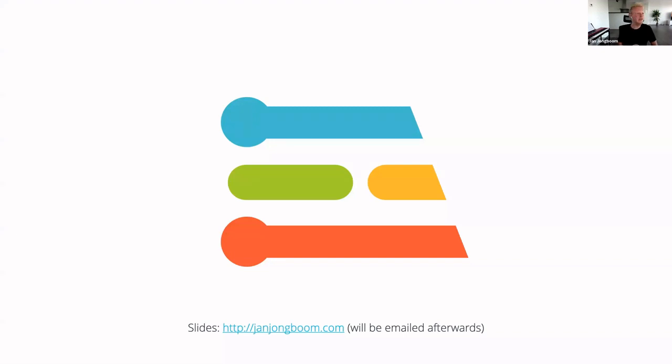What we see is Cortex M. I would recommend a Cortex M7 for doing this stuff because it will just run fine. If you have a very specific use case, it is possible to build a model that is small enough to fit on a Cortex M4. But typically M7 and above can do this stuff in real time, 10 frames a second even sometimes.